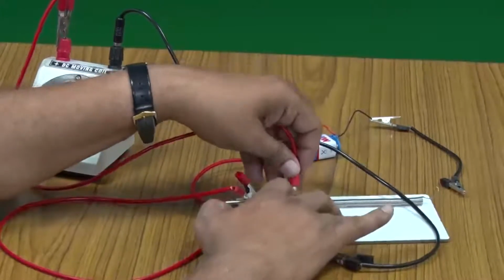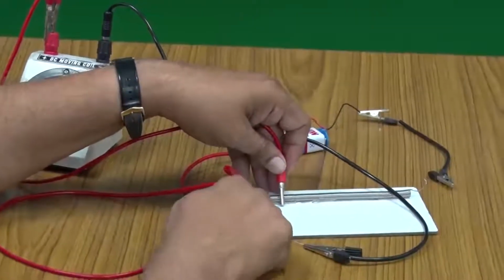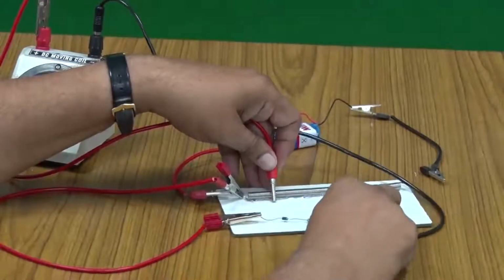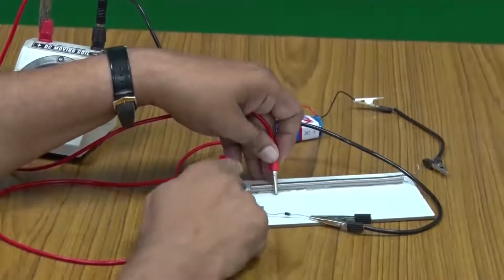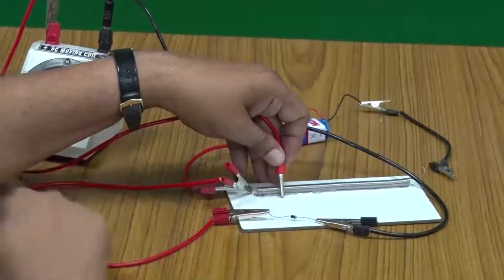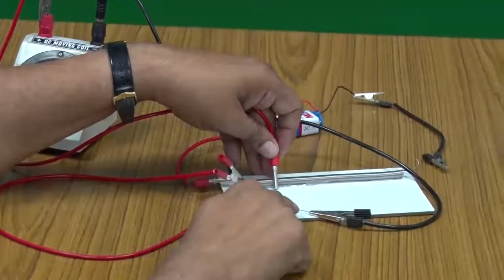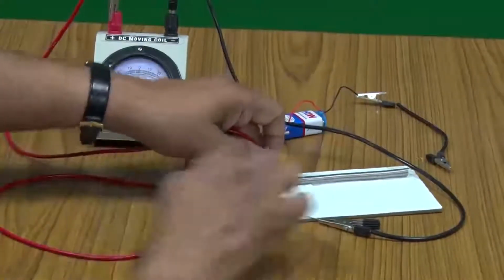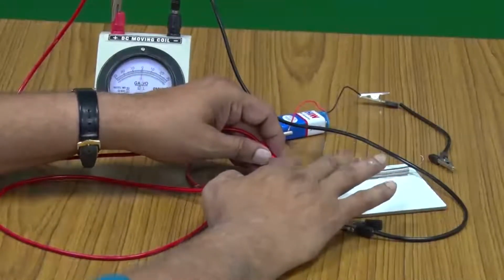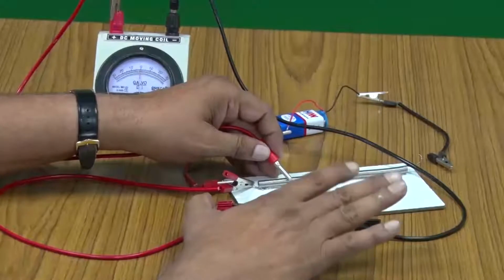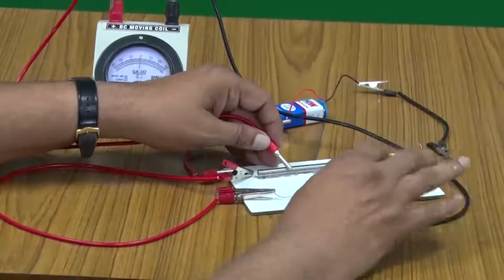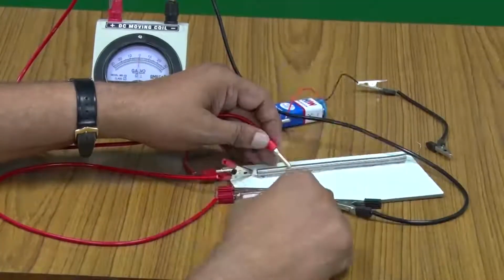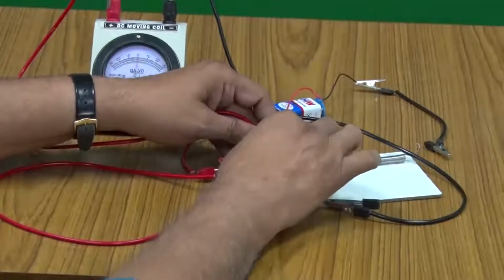So, suppose this is that potential source here, and then from the positive side I am connecting it to the P side of this diode. This is the P side without the silver band. From the positive of this potential I am connecting it to the P side, and then the N side is going to the galvanometer, and then back from the galvanometer to this lower potential side. So, this is a forward bias situation, okay, and the potential that I am giving to this diode, of course the resistances etc. are there, will be just this much, whatever potential is on this.